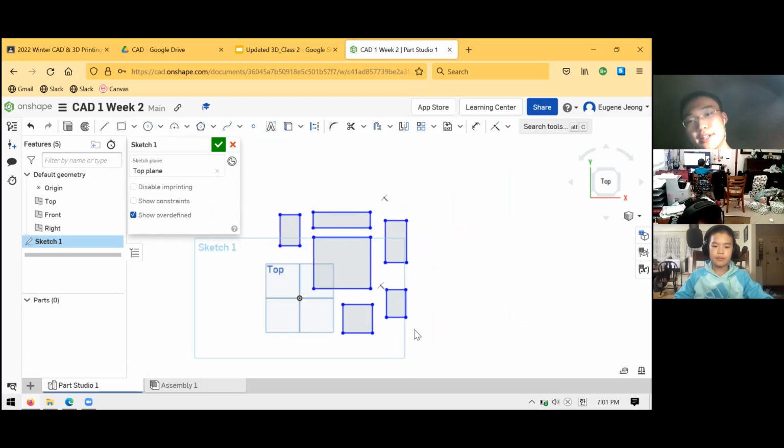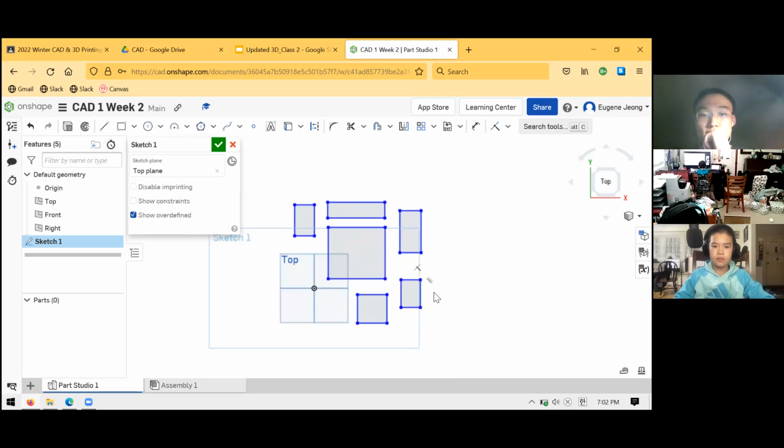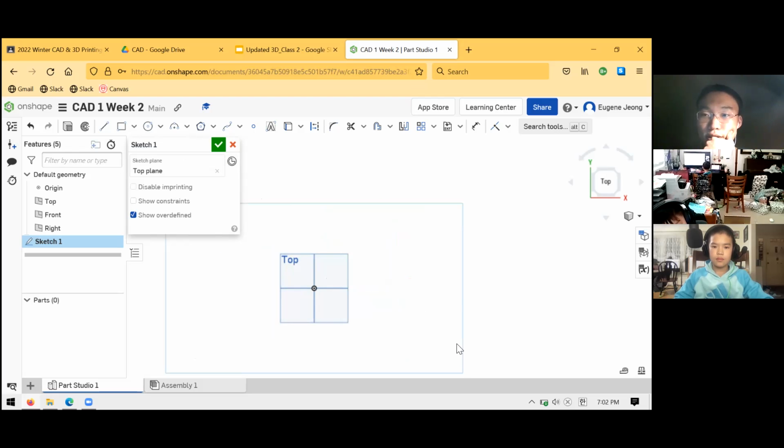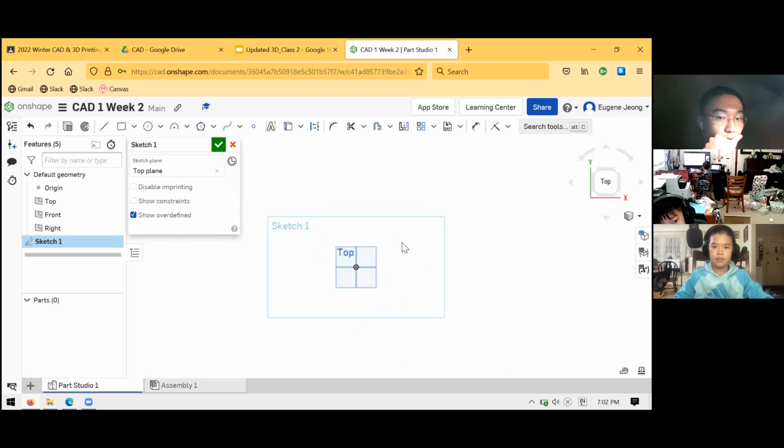So you can imagine if you needed to make a bunch of rectangles, instead of using the line tool 4 times for each rectangle, it's a lot faster to just click and make a rectangle that way. And it's the same idea. These fundamentally are the same type of sketch objects, which are line segments. It's just that you have a tool that's kind of like a macro. It does it for you, right? Makes your life easier. Same deal, there's nothing different from this than the lines. You can delete them just by selecting and deleting. And that's kind of what you got.